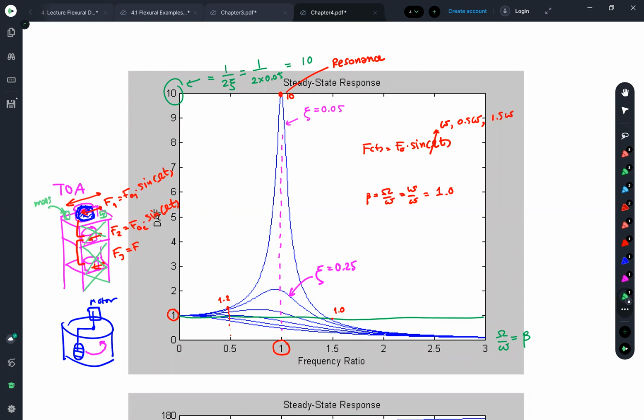It is one of the good alternatives, but still you have to pay some money for adding the steel frame or bracing like this. That is a good idea. One of the good ideas, I think, to change the frequency of the building: modify the mass, modify the stiffness. Any other idea?